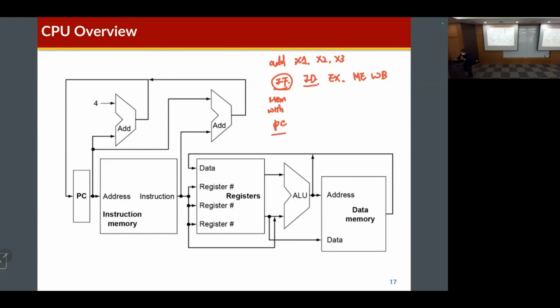In instruction decoding, we first decode the instruction, and then access the register file for reading. In execution, we perform operations like arithmetic or logical operations. To perform these, we require the arithmetic and logical unit, called ALU.